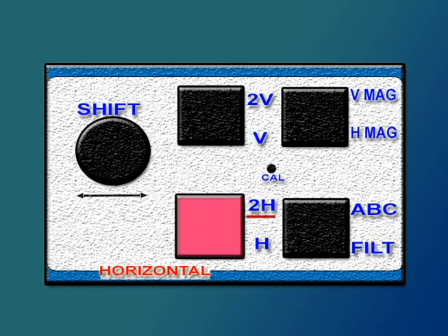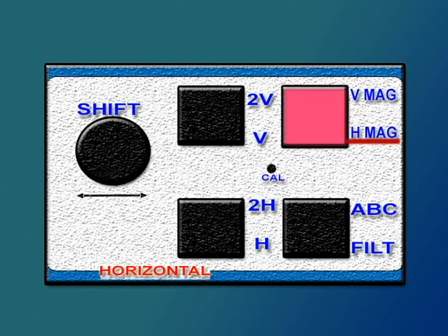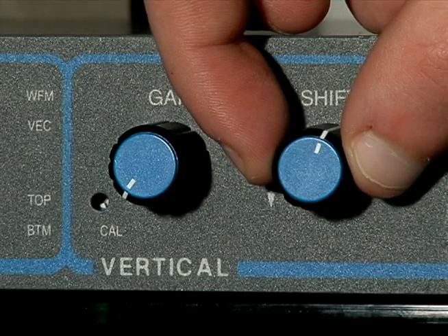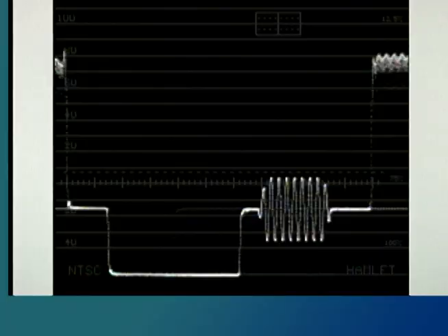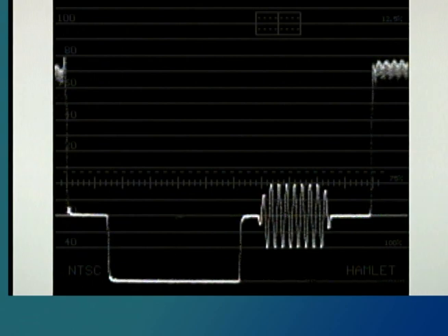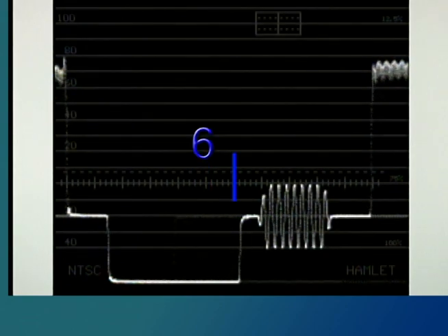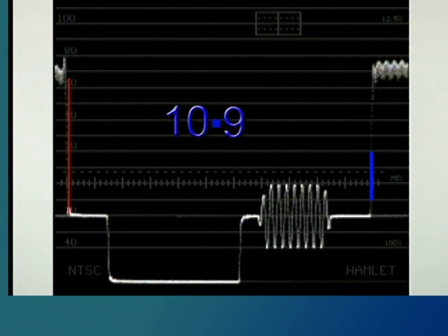Set the control to 2 lines, 2H, then select the HMAG. Position the blanking level at -20 IRE. Always remember this when measuring the horizontal blanking. Where the waveform crosses the graticules at the two locations is the horizontal blanking. Use the graticules to measure 1 microsecond per division. The overall duration should be 10.9 microseconds. If it is over or less than 10.9 microseconds, then something is wrong with the signal.